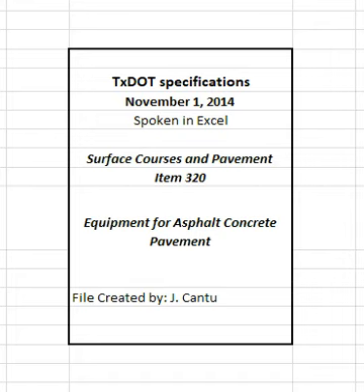2.3.2 Material transfer devices. Provide the specified type of device when shown on the plans. Ensure the devices provide a continuous, uniform mixture flow to the asphalt paver. Provide windrow pickup equipment, when used, constructed to pick up substantially all roadway mixture placed in the windrow.